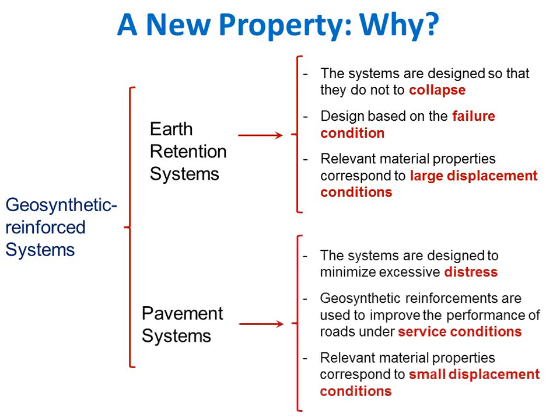While when we are dealing with pavements, what we really need is to understand relevant material properties, maybe deformability properties, under small displacement conditions or small strain conditions. But it's very, very tricky because we really are dealing with a composite. We're dealing with a soil reinforcement interaction. And if it is hard to quantify failure or strength, it's even harder to quantify deformability.